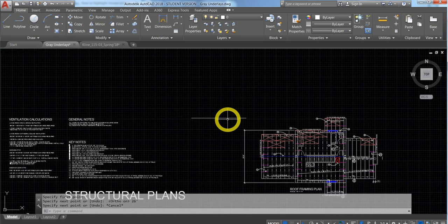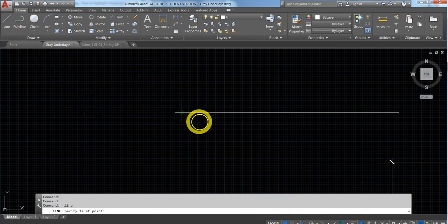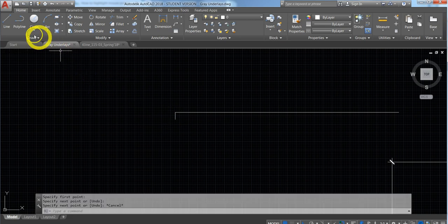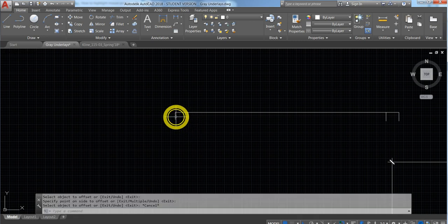Okay, and so this is the overall length of my truss. And then again, we offset. So I'm just going to draw a quick little guide line at the very end here, and the very end here. Doesn't matter, this dimension. So I'm going to offset this line 18 inches or 1.5 feet, because again, this is where our truss is sitting on our wall. So again, it'll kind of start making sense in a little bit.